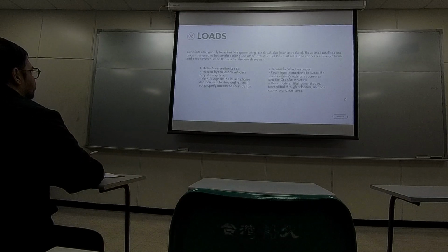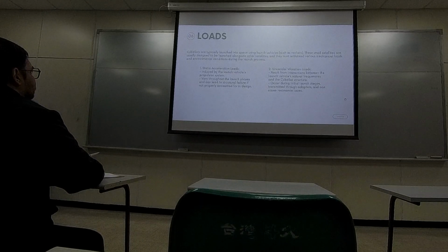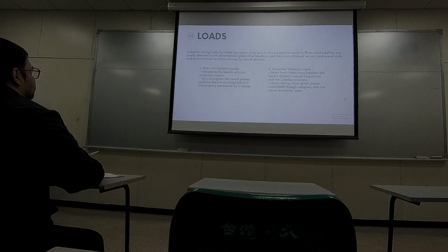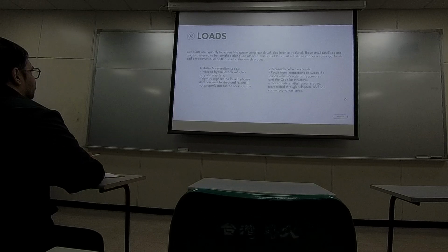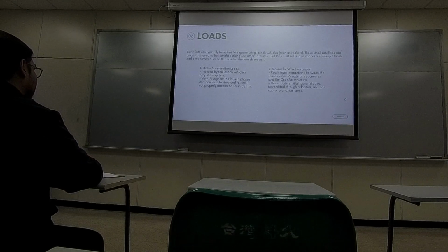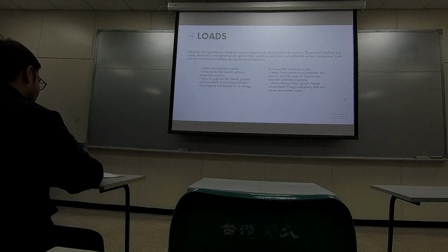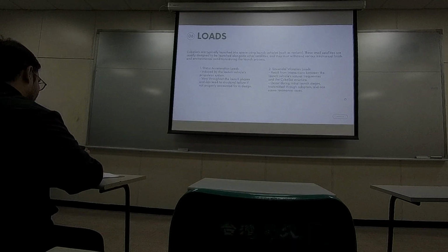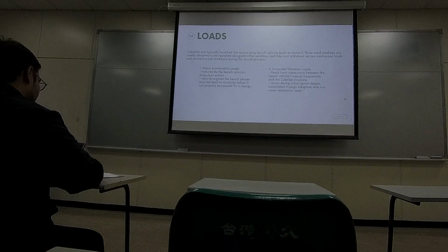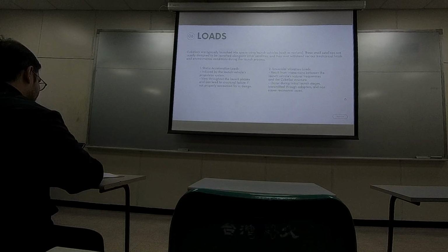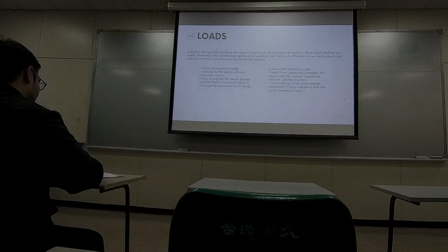So the first load is static acceleration load. It may be induced by the launch vehicle's propulsion system, and it also varies throughout the launch process and may cause structural failure, and it may crack during the process. And second, sinusoidal vibration load. It results from interactions between the vehicle's natural frequencies and the CubeSat structure. It occurs during the initial launch stages and can cause resonance issues.